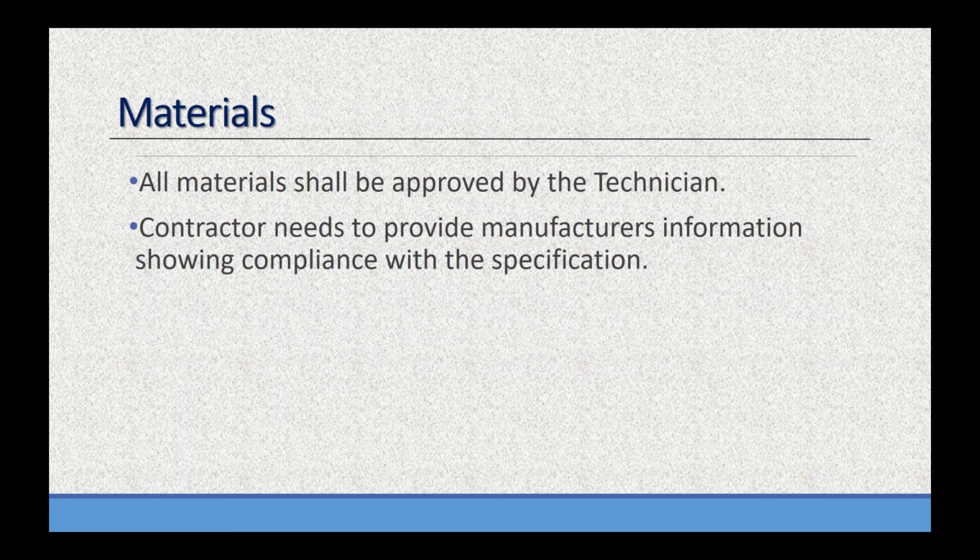And the contractor needs to provide manufacturer's information showing compliance with the specification. So stuff like what the water stop's going to be, how am I going to weld it, any materials you want to identify that well up front, well before we're thinking about pouring any type of concrete.